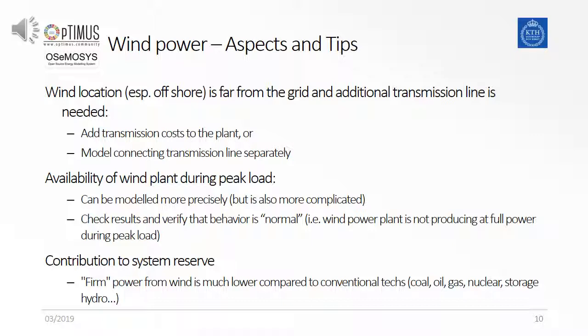The peak load and the wind power peak capacity may coincide at some points, but it is unrealistic that they coincide every time. Wind power plants are also not as firmly adding to the system capacity reserve as power plants that are more conventional.